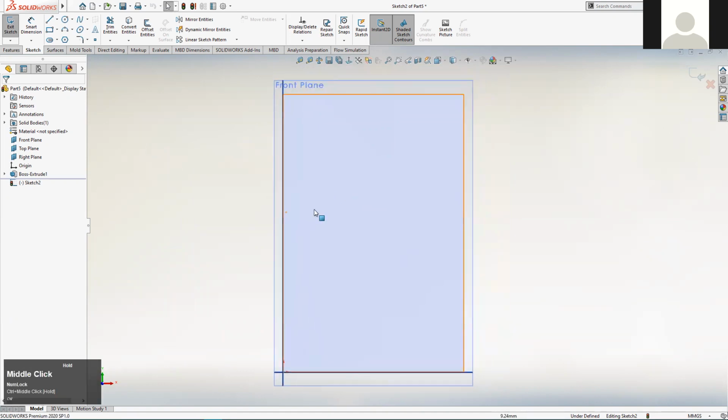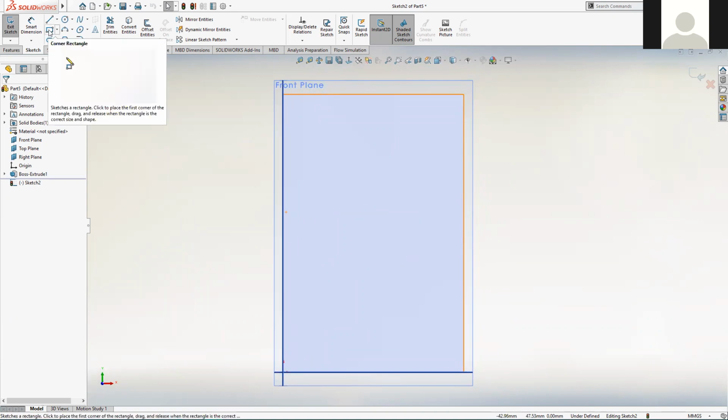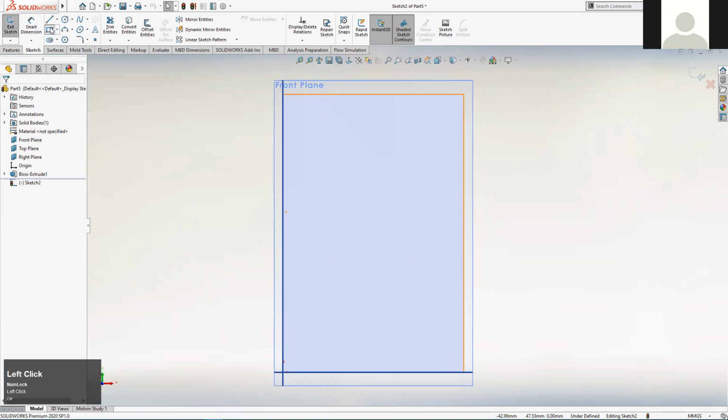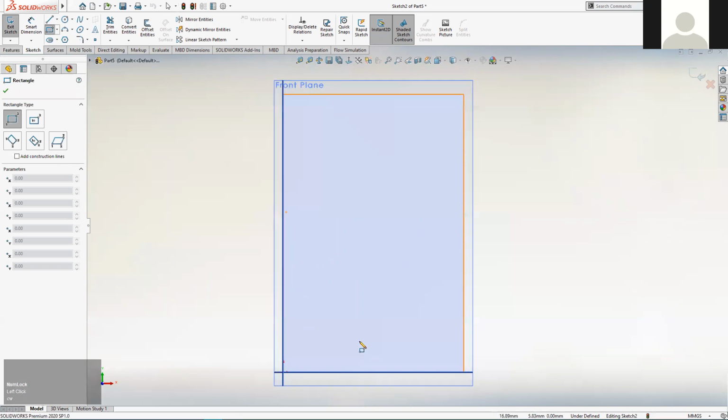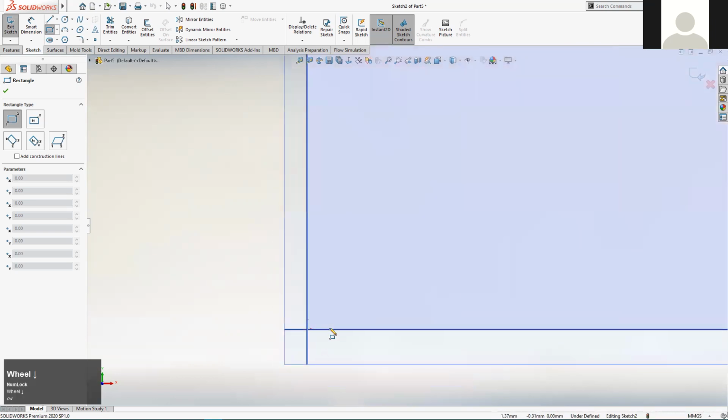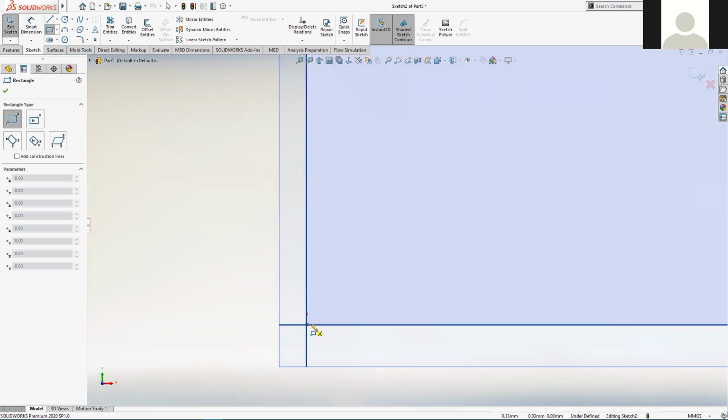So we're going to create this sketch. It's just going to be a corner-to-corner rectangle again. So if we get that tool again, that's the tool that we're using because we want to lock one corner down here onto this point, which happens to be right over the top of the origin. You can see the origin there with two little red arrows indicating Y and X direction away from the origin. So I want to lock one point so it's coincident with that point there.